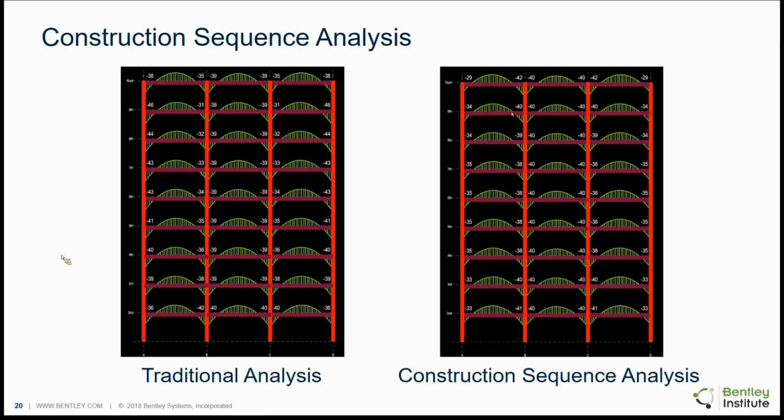When we input the stiffness and the section properties and all of that, it's very rare that we would also include the stiffening effects of the reinforcement in our structural analysis model, because we don't know what it is until after we've analyzed the structure. So historically, we've ignored it for all aspects of our analysis. Just a thought that occurred to me.